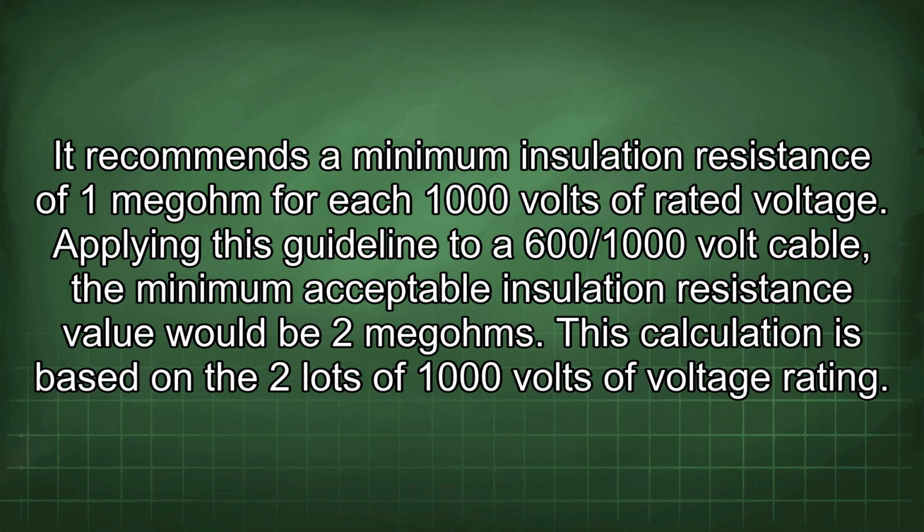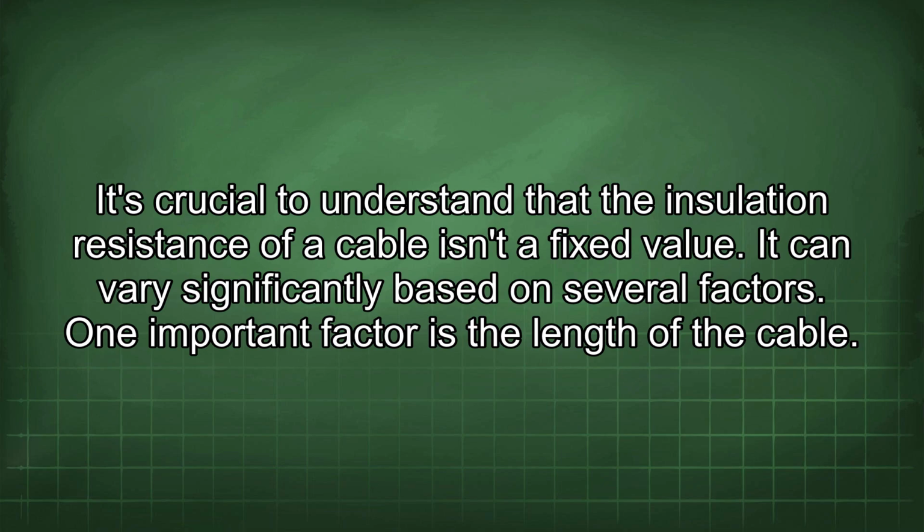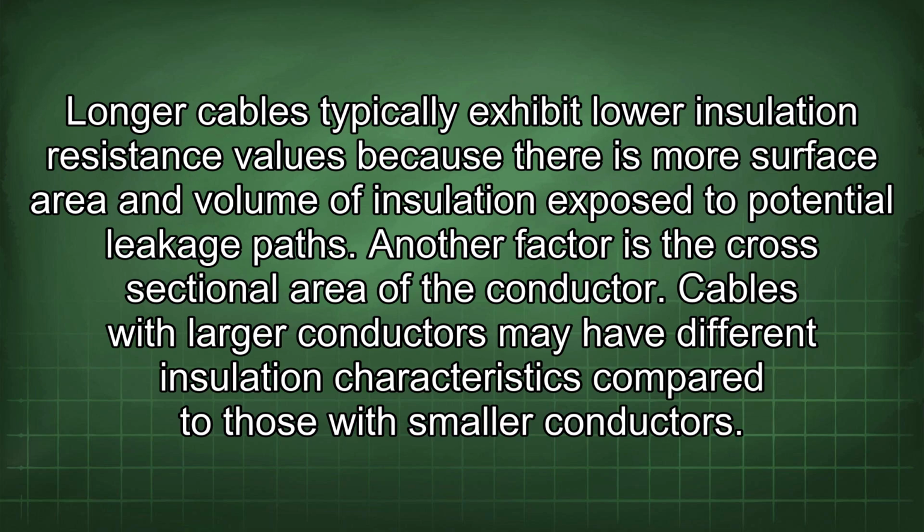This calculation is based on the 2 lots of 1000 volts of voltage rating. It's crucial to understand that the insulation resistance of a cable isn't a fixed value. It can vary significantly based on several factors. One important factor is the length of the cable. Longer cables typically exhibit lower insulation resistance values because there is more surface area and volume of insulation exposed to potential leakage paths. Another factor is the cross-sectional area of the conductor.